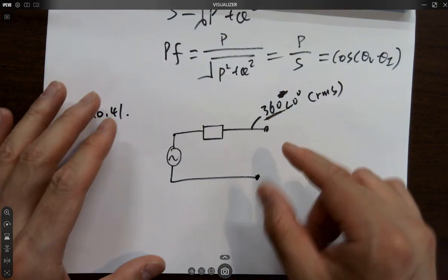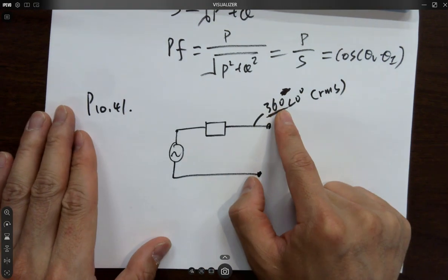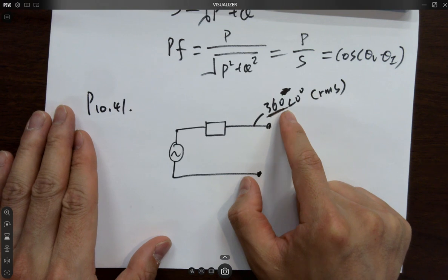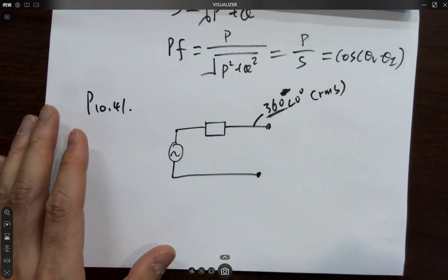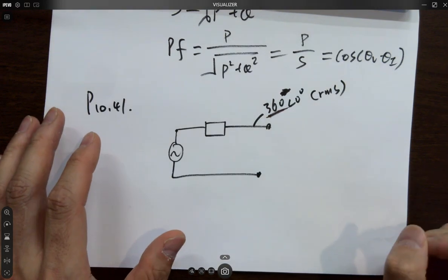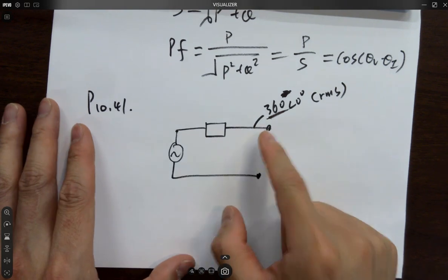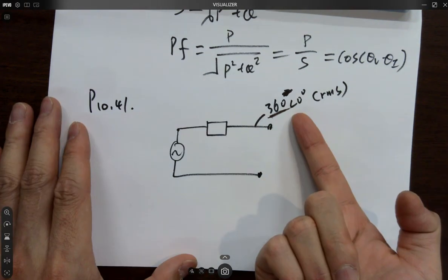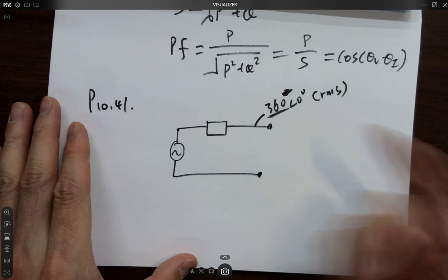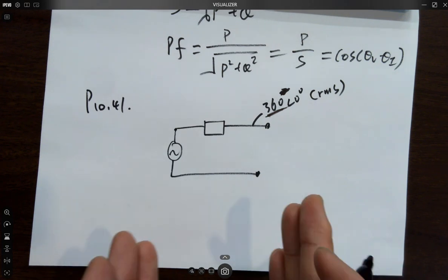It's telling you that I got a circuit, and when there's no load, I read the voltage as this. Is that something familiar to you guys? So in Thevenin's equivalent, when we try to find out the VTH, what do we do? We remove the load and find out the terminal voltage. So we know the Thevenin voltage, right? I tell you, when there's no load, you got a voltage like this. So what is this voltage? That's the Thevenin voltage.